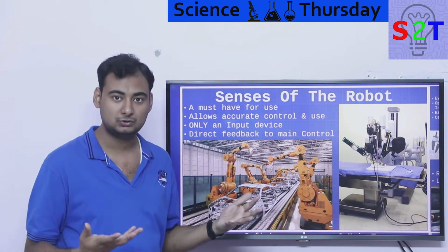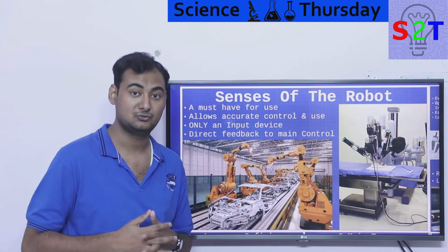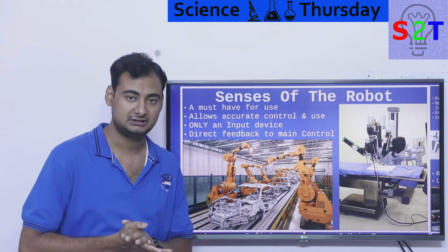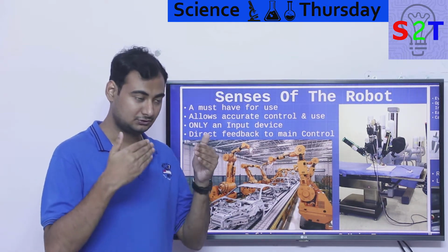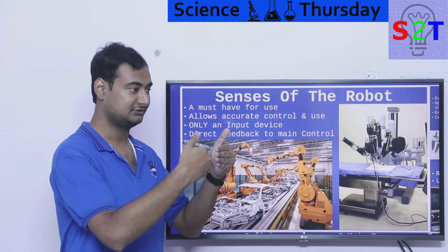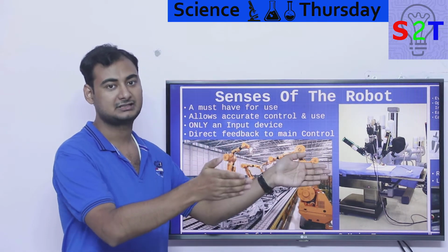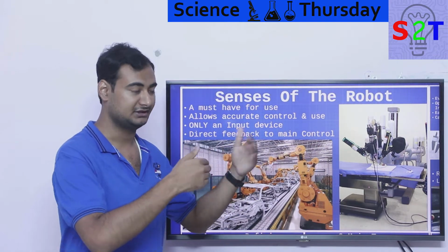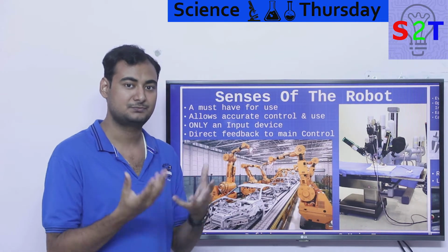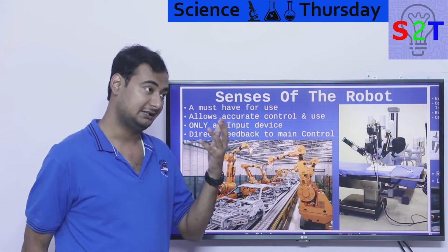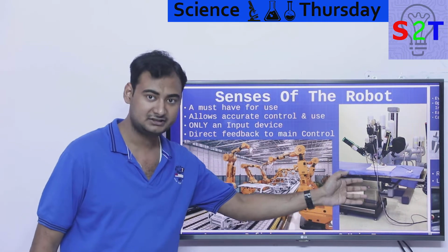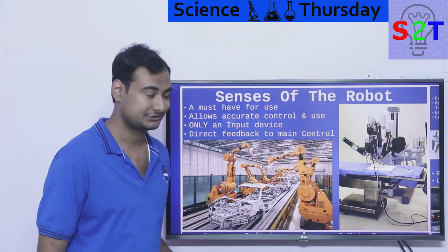Can you make a crude robotic system with, let's say, a pneumatic system? Yes, absolutely. In my pneumatics video I provided the example of doors on a bus, where the valves only work in absolute scenarios: keep opening until it reaches a limit switch when the valve is closed, and doing the opposite when you want to close it. There is no feedback, there is no precise control. Now again, if that's your use case, awesome. But if you want to do something like a welding robot or a medical robot, you have to have encoders.